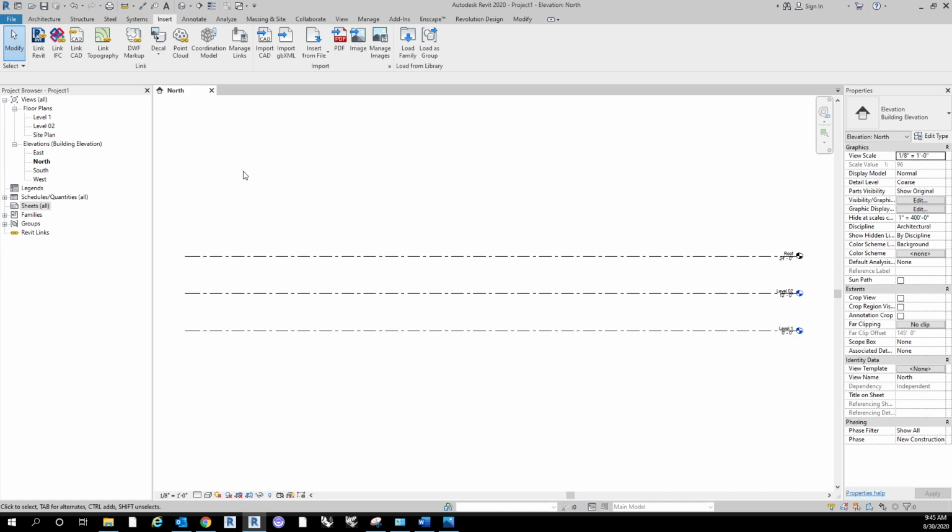Okay, so if I'm working in the office model, I will have linked in all of the other models into it. The reason you do that is you keep your file size significantly lower if you're not working on multiple fully detailed projects, right? So you want to break those up into their individual buildings so that it keeps the file size low, but yet you can link them in so that you can still see the different relationships that they have between the two.